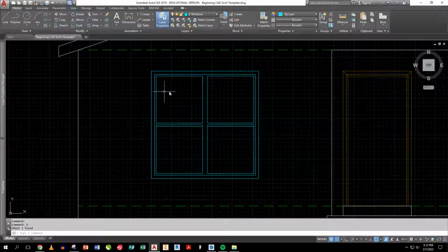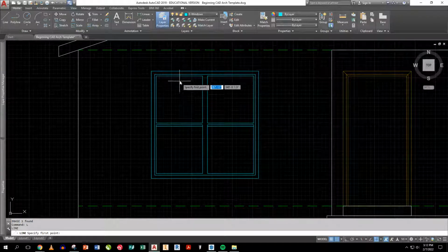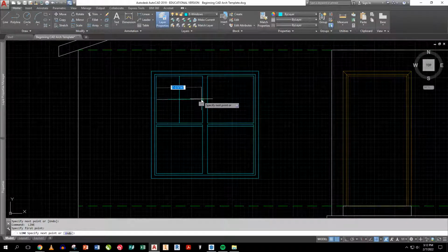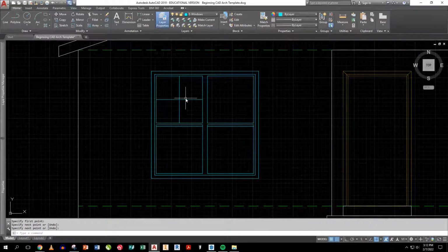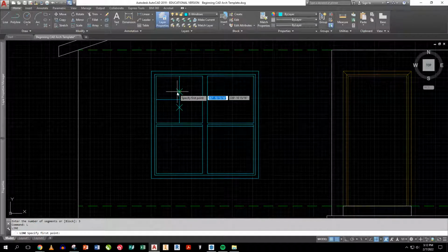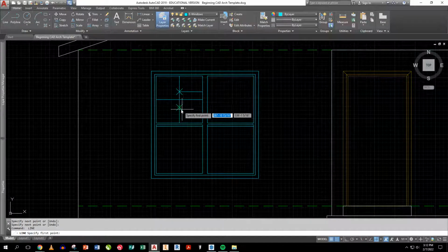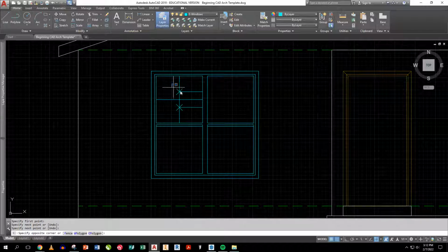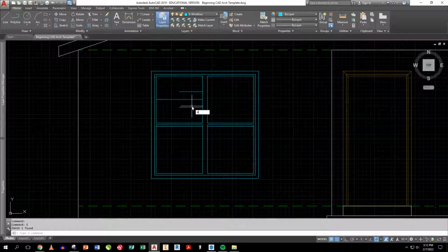So now if I want to divide lights, I can literally make a divided light into it. I typically do a 3x3 when I do something like this, but to do that, I first have to make some construction lines. I'm literally going to throw those up just like so, and then use the divide command, okay? And I'm going to divide this line right here into 3 chunks, and go line from here over, and from here over. And then I can erase this portion, and this line actually, and then I'm going to divide again,